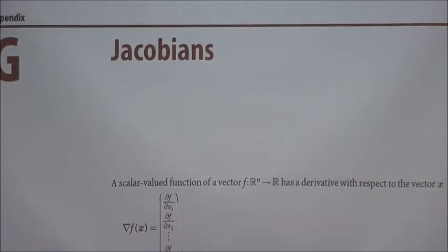In order to do that, you need to find the Jacobian of your pose of the robot. You see, pose meaning location x, y, and the direction, these 3 variables. And in your homework number 4, you have an x and a y and a theta, which are your state variables. And the velocities of the rear wheels of the robot on the left-hand side are your control variables.